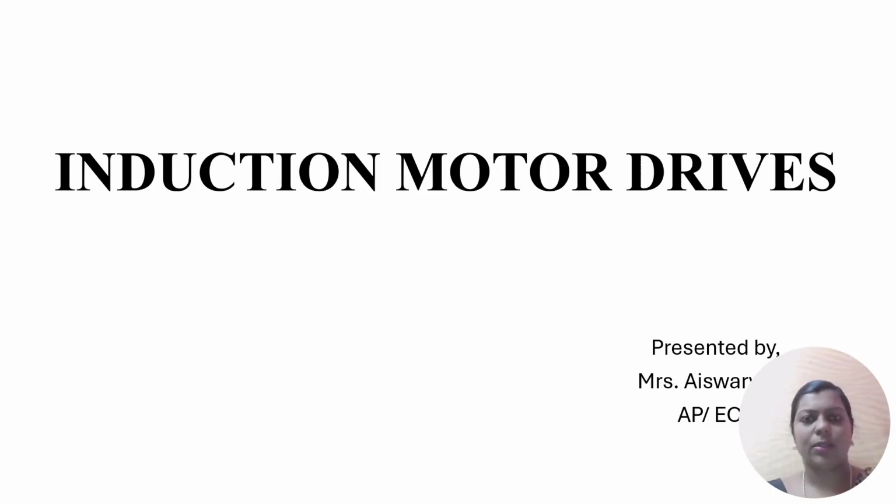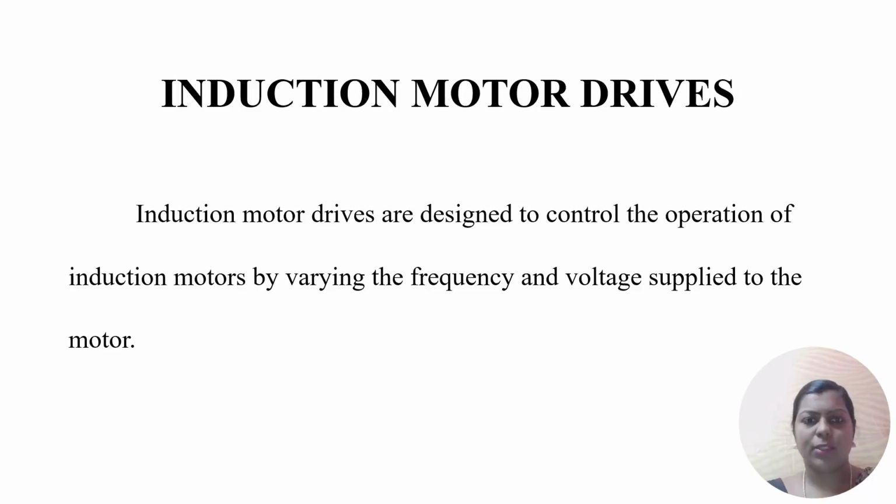And today I'm going to introduce you to the topic of induction motor drives. Induction motor drives are designed to control the operation of induction motors by varying the frequency and voltage supplied to the motor. Induction motors are AC motors, and in AC motors we need to control the frequency and voltages. They should be controlled and varied according to the usage, and for that matter, the induction motor drives help us.